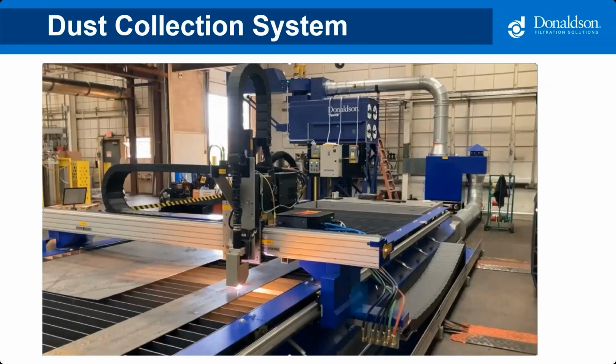Here's a real-world example of a dust collection for a laser table. Okay, technically it's a plasma table, but they're both metal cutting tables, and a great example of what you can see, the entire system here. As you can see, it has a downflow airflow draw. And you can also see the ductwork on the right side pulling air through a custom spark mitigation system into the dust collector.